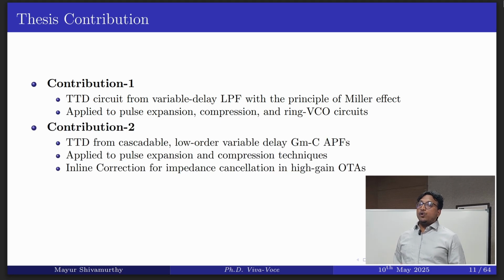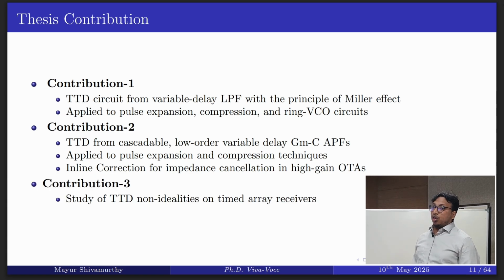The next contribution is the realization of a TTD using a lower order GMC all pass filter. The principle will be further expanded to pulse expansion and compression techniques. We have also proposed a new inline correction technique for the impedance cancellation in high gain OTA. And the last contribution of the thesis focuses on the study of TTD non-idealities on a time delay receiver. So let us now go through each of the contributions one by one.